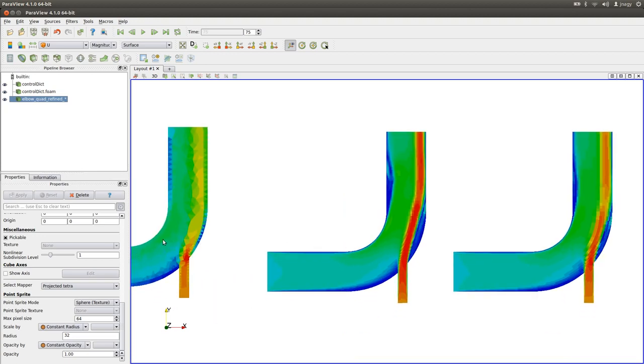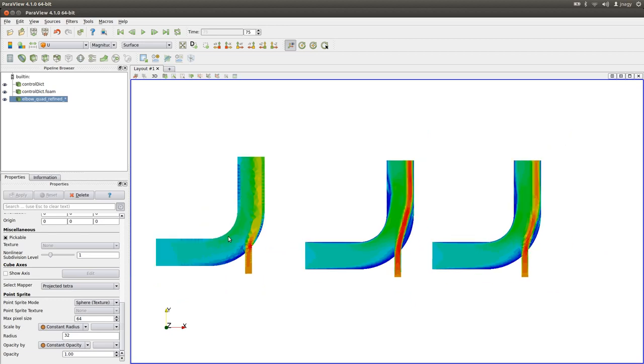So this is the reason why it is very important to think about your calculation grid and the quality of your mesh. Obviously, this mesh is not very good for that. In order to depict large scales, that the velocity is going here in the positive X direction and here in the positive Y direction, and then here something's happening, then this grid is good enough.